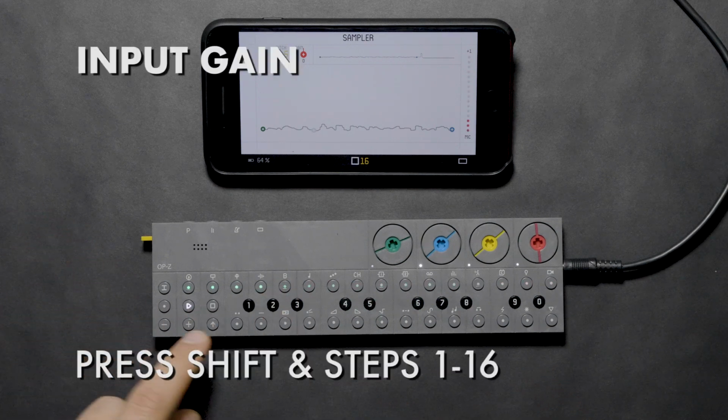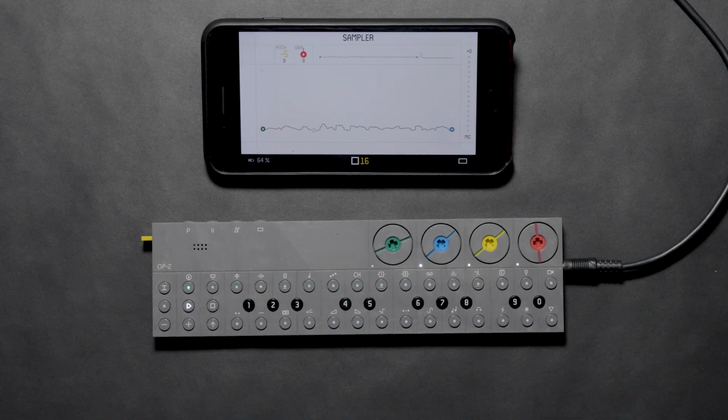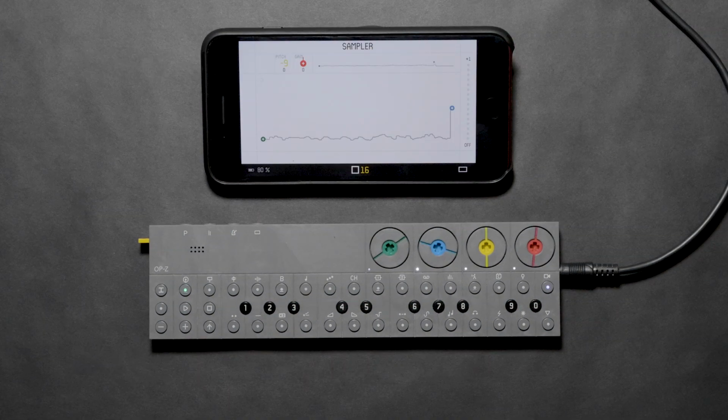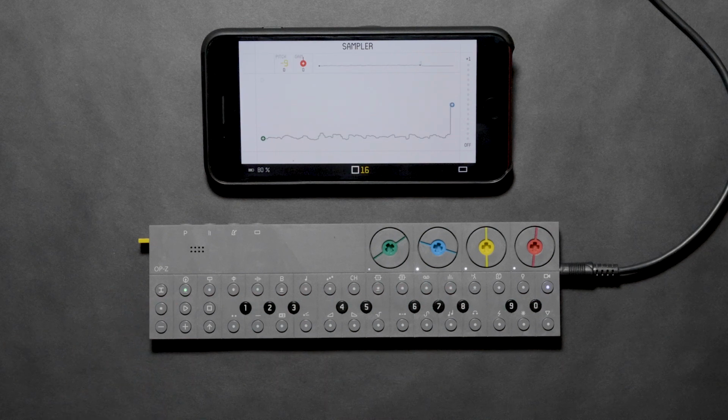Input gain can be adjusted by holding down Shift and selecting a step between 1 and 16, 16 having the highest gain. When you're ready to record, press and hold record. This will start recording the sample and it will finish when you let go. During the recording, the red LEDs displayed on the step sequencer will show you the length of your sample and the allowable time left. Now we have our own sample loaded into the OPZ.